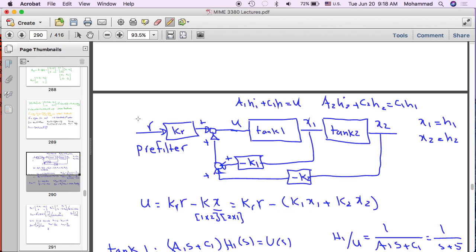Did you see the logic here? So we see that with KR of 1, our steady state response output gets to 1/20th of where it's supposed to be, 0.05. So if we scale up the actual R value, we are going to make the system go to 1/20th of that value, which is exactly what in the first place we wanted the system to do. So change that 20 in your simulation and simulate it. But this time KR was 20.